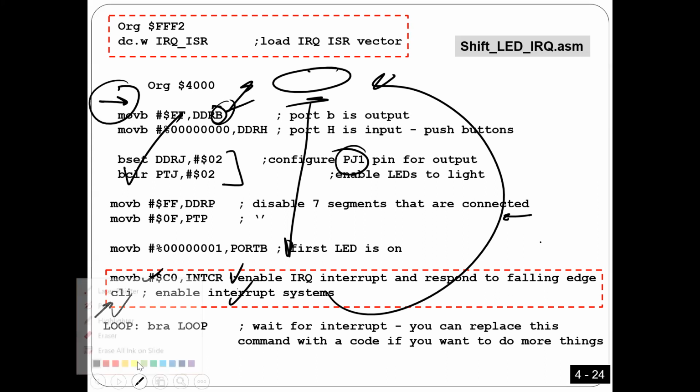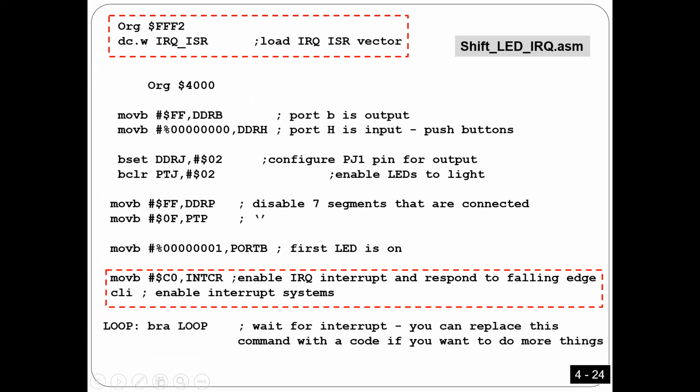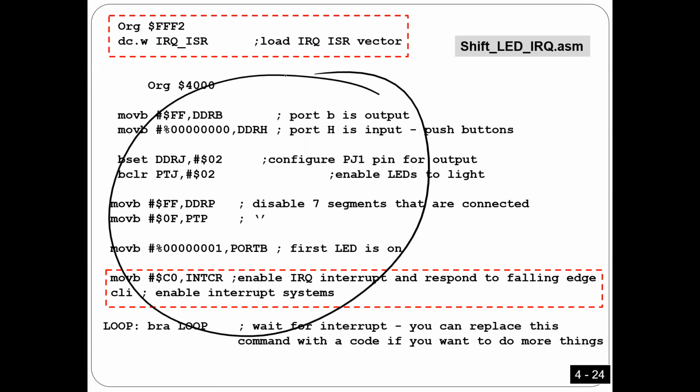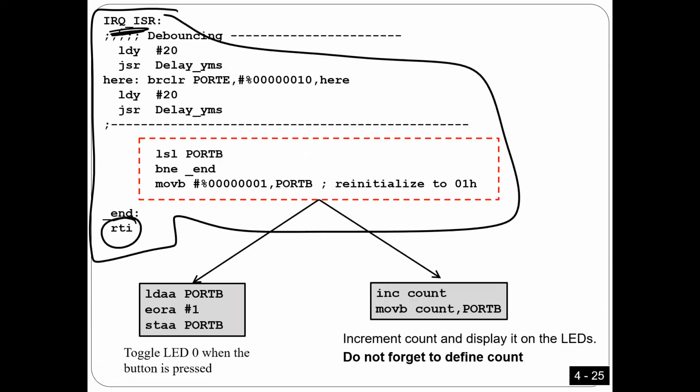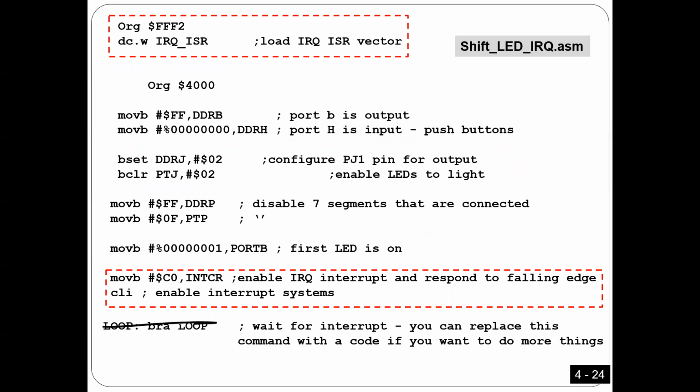Okay, and then here, because this is a very simple program, in the main program I actually run only one task. This task is written in the interrupt subroutine. The main program doesn't have another task because this is very simple. However, you can remove this and put any other task here, like for example the keypad and LCD lab, or any other task as we'll do in the future. Now this is just a very simple program. I don't put anything in the main program, but in the future, it's free. You can put any other task there.